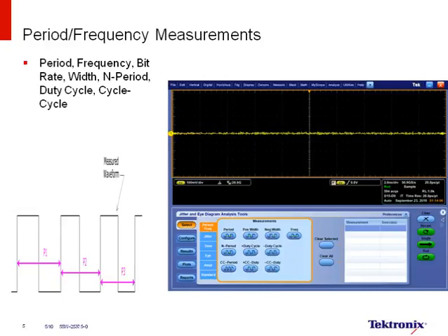So slide number 5, cycle-to-cycle is defined in this case to be, if you look at the diagram to the bottom left, P2 minus P1 or P3 minus P2. That's a cycle-to-cycle jitter measurement, and it can have peak-to-peak, and it can have standard deviation. So cycle-to-cycle is a type of measurement, and peak-to-peak is the statistic related to the type of measurement. And remember, you will get my email address, so I'm sorry we're out of time.